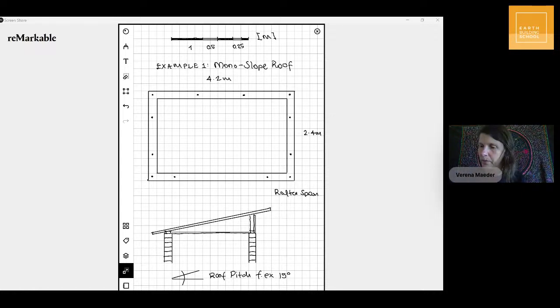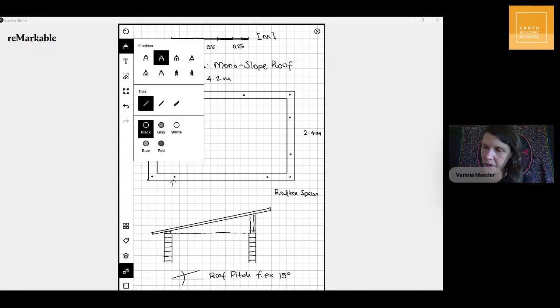But you still have the situation where you have a top plate and then your timber roof attaches to the top of your wall. And in this example, you see, the wider earth walls have got some reinforcing steel. So these little dots here are reinforcing steels.